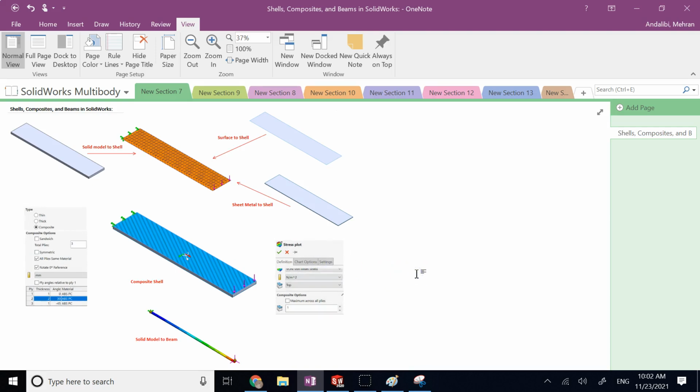Okay, composites, yes. So you can have basically different plies, different layers, and in each ply you have your main filament, right? Could be from any different material, from carbon fiber or anything else, that are kept together in the resin or any material that is acting like a glue, holding them, bonding them together in a layer. And you can have several different layers of composite material where these filaments are going to be at different angles. So you can create composite material for static analysis.